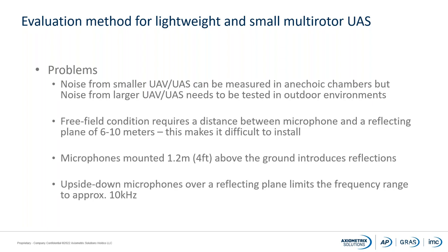If we're using the 1.2 meter or 4 feet above the ground, that will introduce reflections, and that is not really good if you have a stationary source or if you have tonal content. Then we can also use this upside down microphone, but that is not going to work for frequencies over 10 kilohertz. So regardless of what we already have in the standards, it's not really useful for doing accurate measurements on UAS.